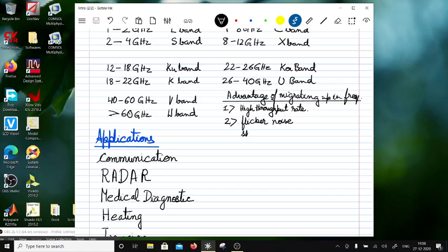Next thing is the shot noise. Shot noise is whenever there is a p-n junction, then the carriers which are crossing the p-n junction basically cross in bunches because they take different paths. So when they arrive, they do not arrive as a smooth flow of current, they rather come as bursts of these charges, right? The noise associated with this burst rather than a regular flow of carriers is known as shot noise. So shot noise you will see wherever there is a p-n junction.